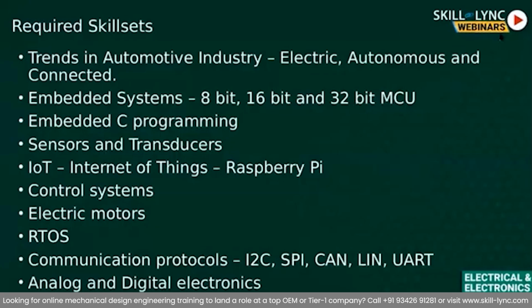Exposure to sensors and transducers and how to integrate these with microcontrollers are sought after skills in industry. I've already mentioned the list of sensors that is available in the car, but don't be anxious or scared by looking at the sheer number of sensors that is available in the car and the fact that you have to integrate all this. You have to just find out how to integrate three types of output from sensors. You take any sensor, it will have either analog output, digital output, or PWM output. And if you have figured out how to integrate these different outputs with a microcontroller, then you are already a sought after candidate in automotive electronics domain.